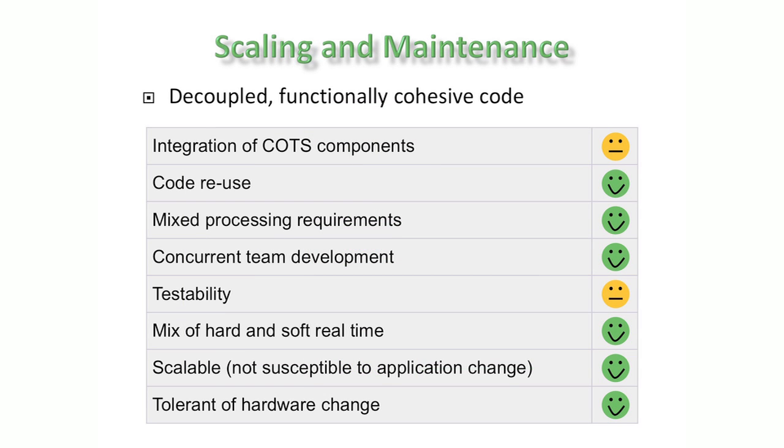What's the benefit of the task-based implementation compared to the Superloop-based implementation? Now, if you can imagine trying to do that same scenario in the Superloop whilst you're handling lots of other things, compared to that, in this example, we've completely decoupled our motor control from anything else that's happening in the system. You might be writing to a flash disk somewhere else, or the speed of the LCD might change, or the speed of your processor might change, put a different crystal on it or something like that. Doesn't make any difference. The kernel is managing all the timing, and the kernel is making sure that this high priority task is always the one that's running, no matter what else the system is doing.